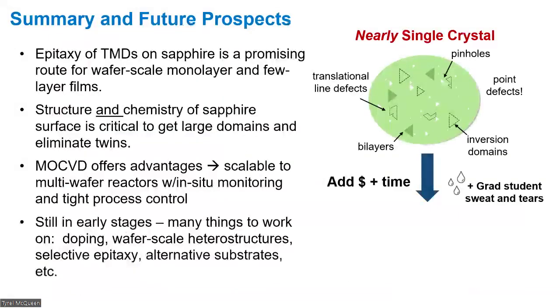Oh, yes. Actually, I left out a step. On top of the PMMA, we also put thermal release tape, which is just another adhesive. So when the 2D layer releases from the substrate, it's still on that thermal release tape, which provides more of a rigid structure.